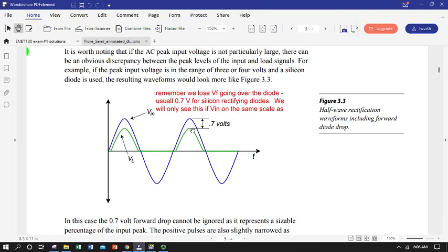So it's like the diode needs a little help. It can only supply a voltage on the forward half cycle. But if we had something else in the circuit that took over the job of supplying voltage once we hit that peak coming out of our forward bias diode, and then supplied something for a time equivalent to, say, one period of our waveform, and then by the time our diode was conducting again on that next forward cycle, it would pick up again.